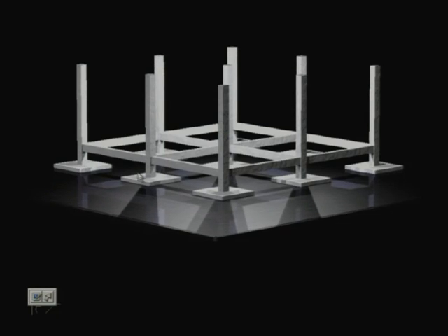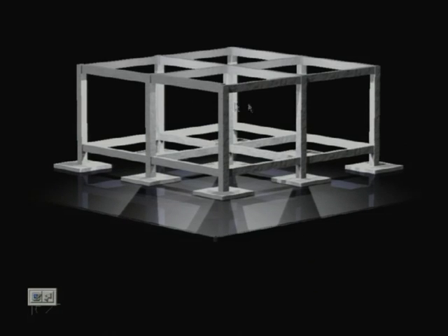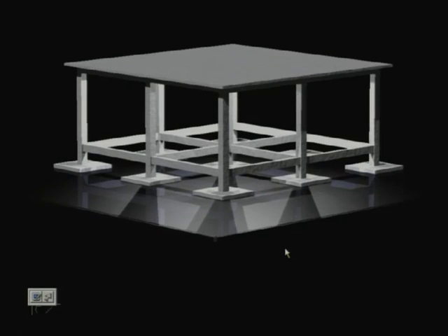Generally, for a wall we do not provide a wall footing; we start from this tie beam, which will take the wall load. We can also take it for the frame, that connection we also consider, but we generally use it for walls. And we have the beams and slab. We construct these beams and slab all together, whenever we cast them, but just to show you, I have made it this way, because if I keep the roof on, we cannot see the beam. So, this is actually how we do the construction.